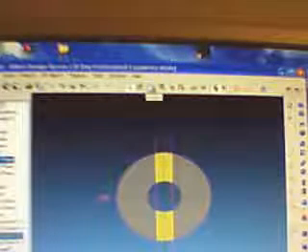Click, another task pane window opens up. Again, I'm going to click in the top left hand box. So it says sketch 2 is what it should say there now. Here in depth, I want to highlight this, and I'm going to type in 0.400. OK, and there we have made an extrusion cut.